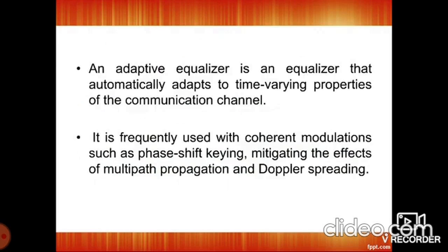So initially we have to know the necessity of adaptive equalization. In communication, most of the channels are made up of individual links. For example, in switched telephone networks, the distortion introduced depends upon two important parameters: one is the transmission characteristics of individual links, and the other is the number of links in the connection. Hence, a fixed pair of transmit and receive filters cannot solve the equalization problem completely. For that purpose, we need an adaptive equalizer.